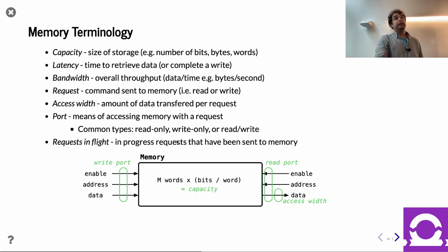Oh, that depends. The question is, how big is a single SRAM array? That really depends on whether you're working from a memory compiler or your foundry for an ASIC. For an FPGA, it's not seen as SRAM, you see it as BRAM. A Xilinx-style BRAM is going to be 32 or 36 kilobits.